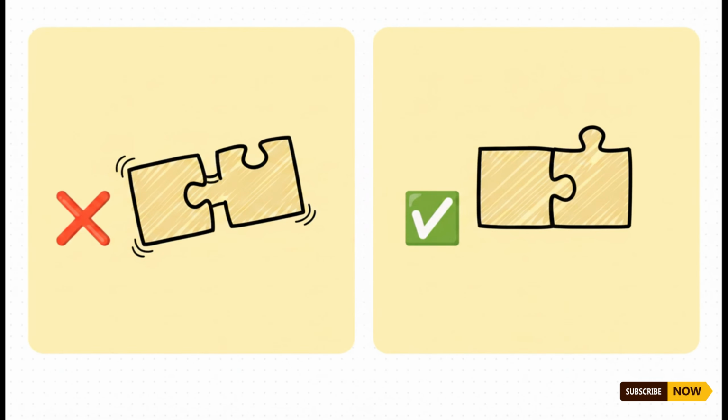Think about the actual difference in outcome here. If you attempt a direct, uncompensated line-to-line fit right out of your CAD software, material gets vaporized equally on both sides of your mating parts. The result? A wobbly, rattling failure that literally just falls apart in your hands. But if you apply proper engineering principles to create a kerf-compensated fit, you change the entire game. By intentionally offsetting your digital cut paths by exactly half the kerf width, you account for that vaporized material, so when those final physical parts come off the machine, they will press together with a beautiful, structurally sound, incredibly satisfying friction fit.